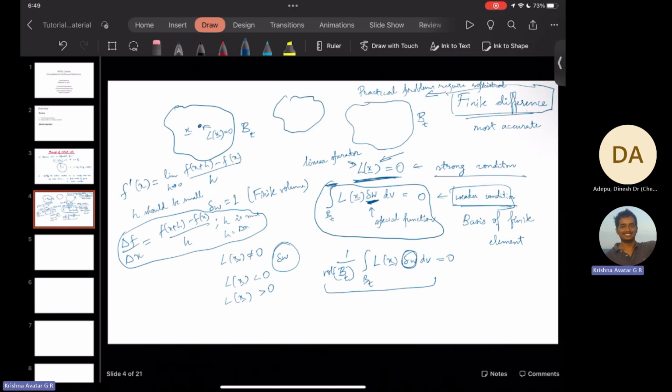However, from a very fundamental sense, finite volume is almost designed for fluid mechanics problems. And the good thing about finite volume is it satisfies the balance of mass. Yes, the equations are exactly conserved. Finite volume exactly satisfies conservation of mass, which is neither satisfied by finite difference nor by the finite element method. And finite difference doesn't satisfy any conservation law.